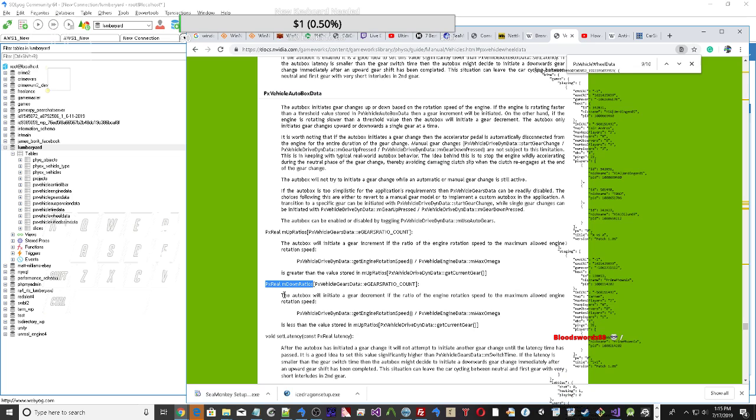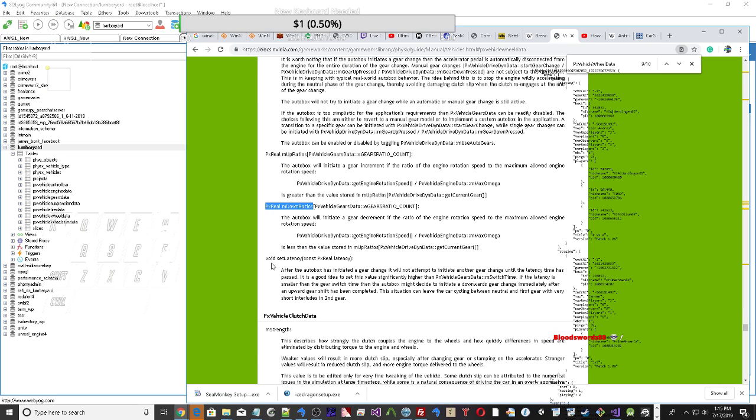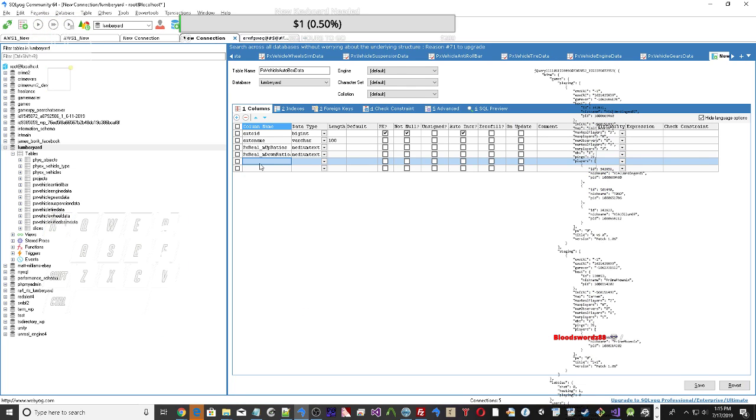The tire force computation actually depends on a number of factors including steer angle, camber angle, friction, wheel rotation speed, and rigid body momentum. The aggregated force of all tire and suspension forces is then applied to the rigid body actor associated with the vehicle so that the transform may be modified accordingly in the next Physics SDK update.